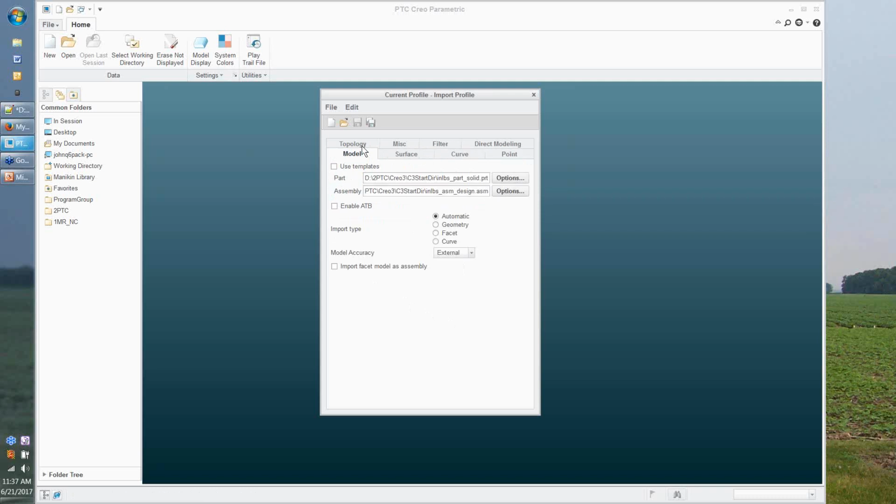The complete flavoring, for lack of a better description, occurs through these settings about how the object is going to be, whatever it is, be it a STEP file, IGES file, Parasolid file, whatever, how we're going to go ahead and import this file, and what settings will be in play when we do that import are governed by either these profiles or the settings you use live on the fly at the time of import.